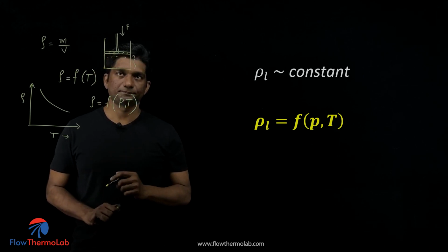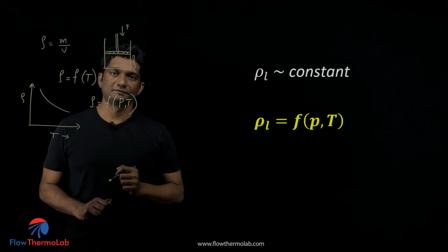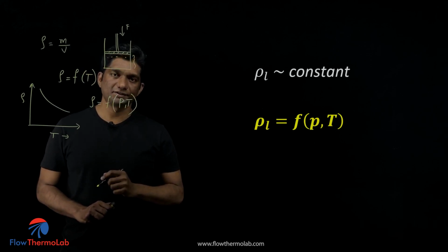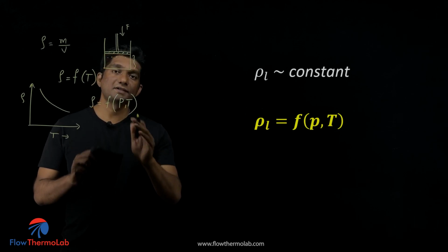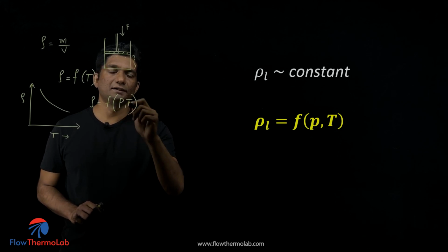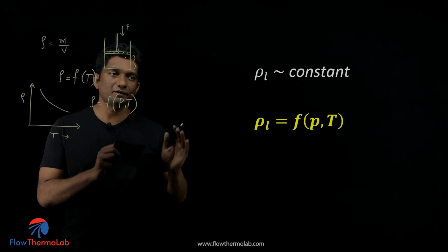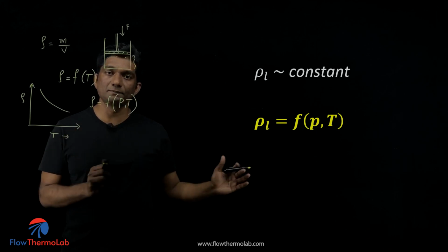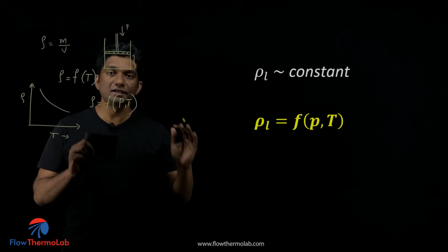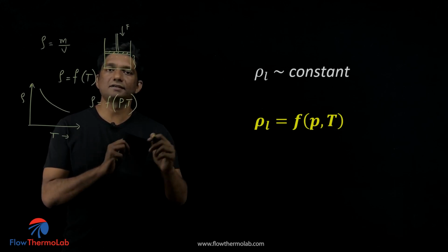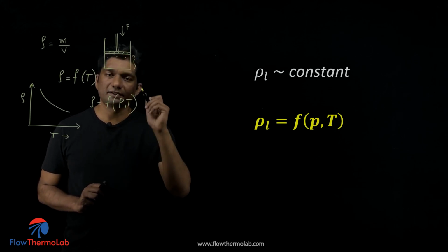It's nearly incompressible. But imagine you are going to apply a lot of force, a lot of pressure. In those conditions, it can really change. These kinds of applications are very few, but still there are applications. For example, in fuel injection systems in diesel engines, you have the injectors and the high pressure pumps, which generate pressure up to 2000 bars. It's really very, very high pressure.